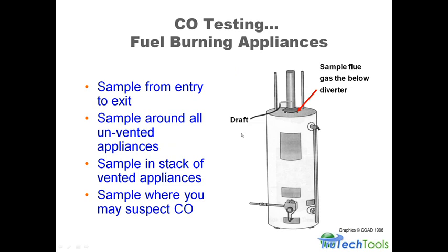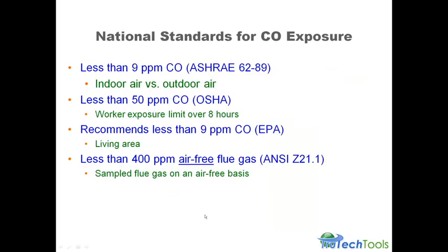There's not a lot of danger with those types of appliances if they're serviced properly, set up properly, installed properly. The problem is Joe homeowner goes out and buys one, puts it in his bathroom, and it's exposed to things like hairspray, and a lack of combustion air because it's in a little tiny room, and the bathroom exhaust fans are competing for combustion air. Those are where we find problems. Those appliances absolutely do need removed. But a properly installed ventless appliance, if it's working the way it's engineered to work, is really not that dangerous at all. But sample anywhere you might suspect CO.